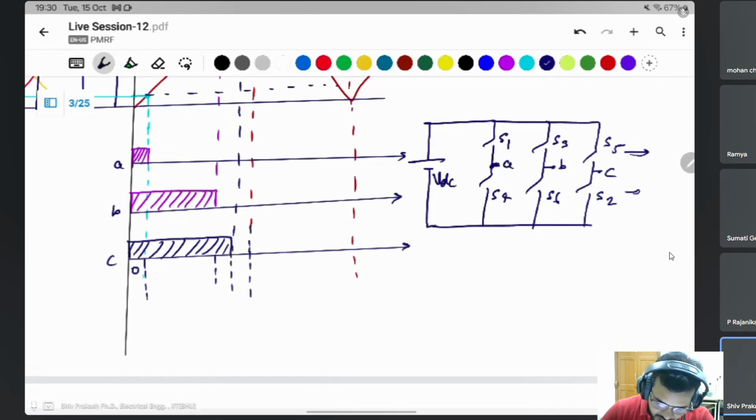Same thing when all of the switches are off, this will be an upper signal. Then 0 means the lower switches are turned on. If this one turns on, then we make only the negative, not a positive. Then this is also 0. These two conditions are the off period, you can say this is a delay time also.